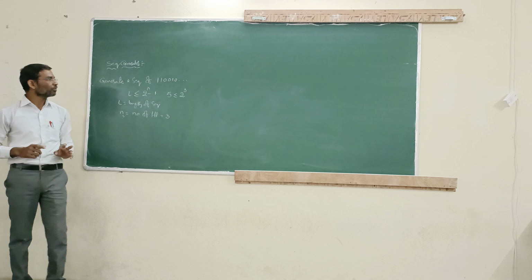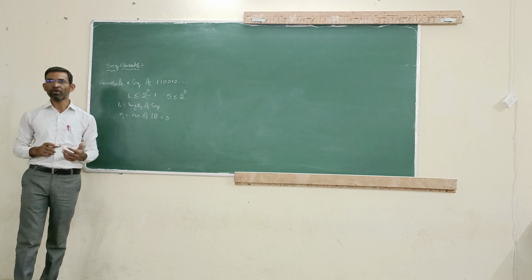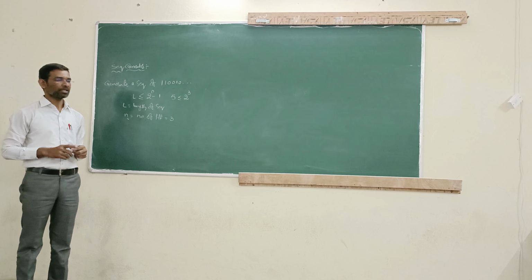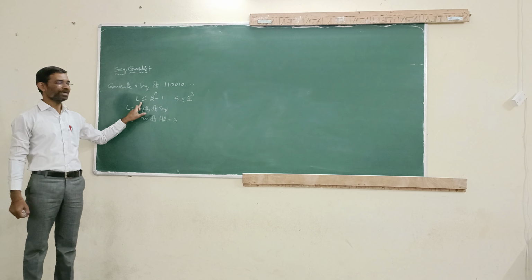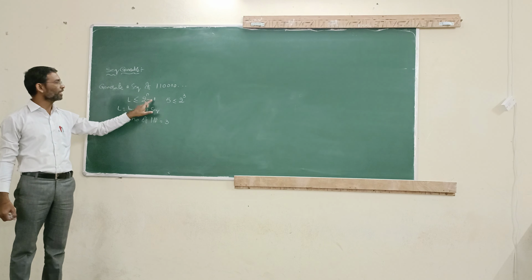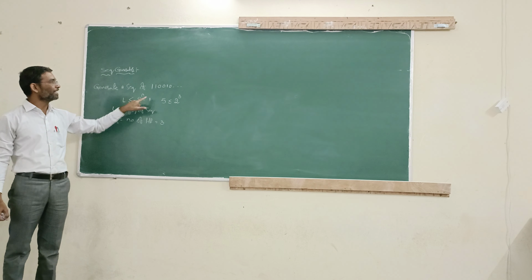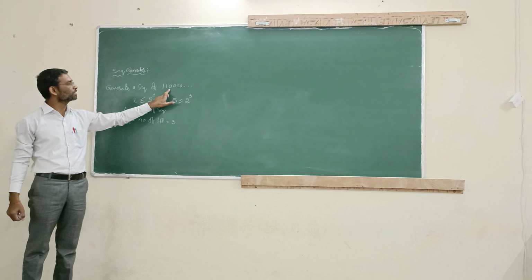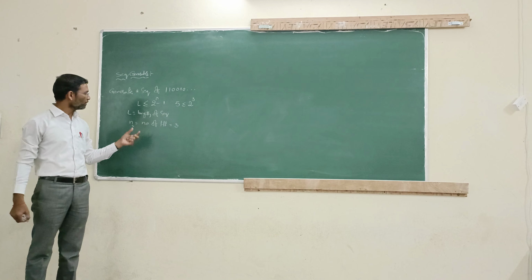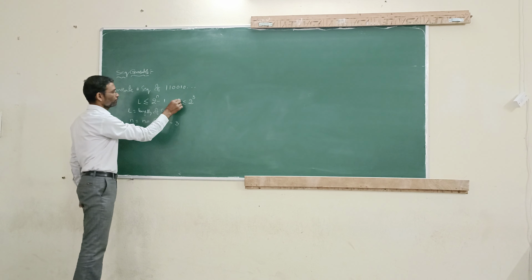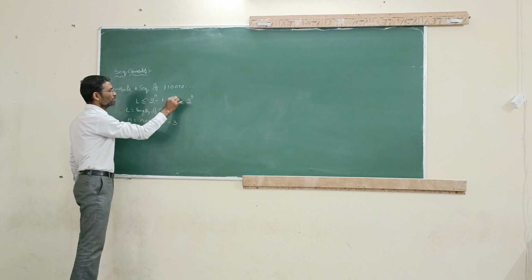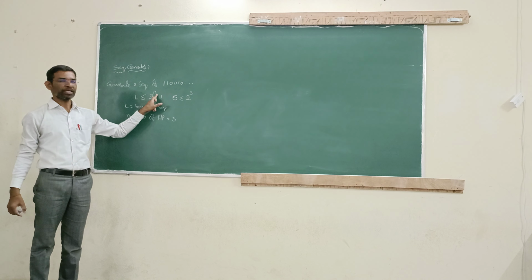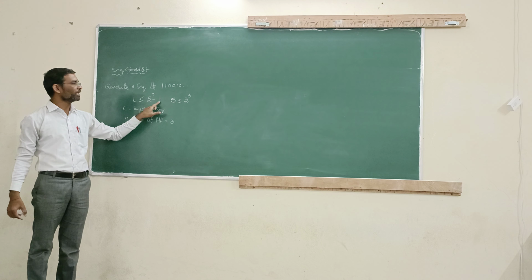Before going to design the logic circuit, here we have to know how many flip-flops we have to use to generate a sequence like this. Further, here we have a condition that is nothing but L less than or equal to 2 to the power of n minus 1. Here L is nothing but number of bits in the sequence. Here how many bits we have? 1, 2, 3, 4, 5, 6. Here capital L is equal to 6. And if you take here n is equal to 3 means, 2 power of 3 is nothing but 8. 8 minus 1 is nothing but 7.